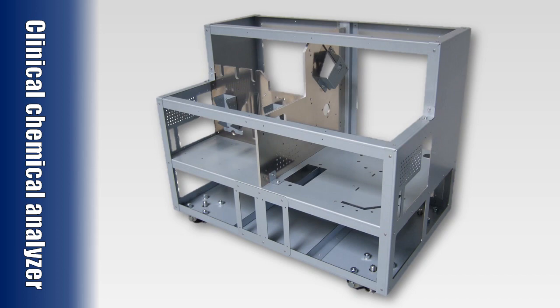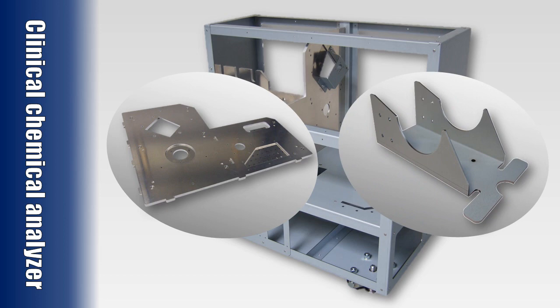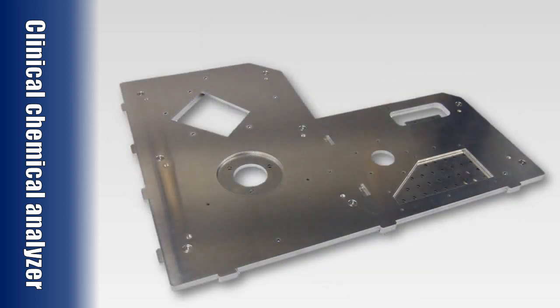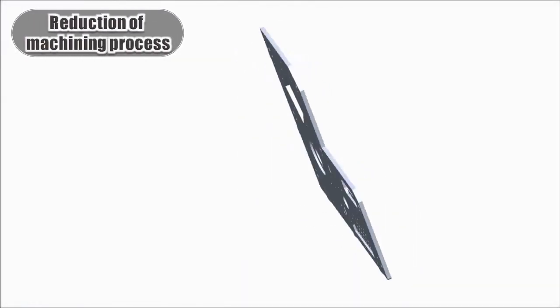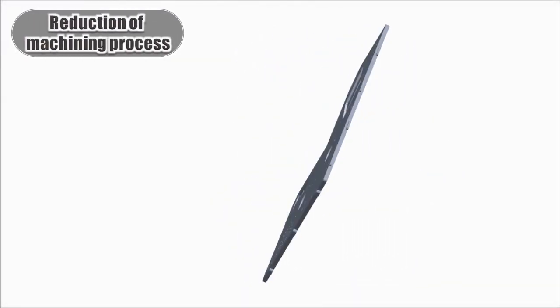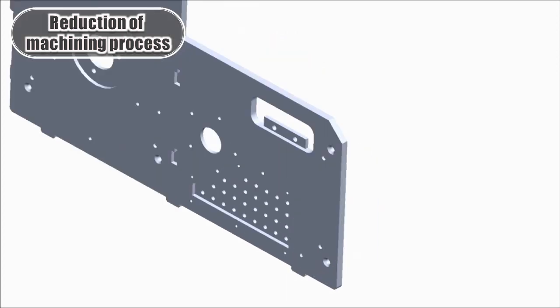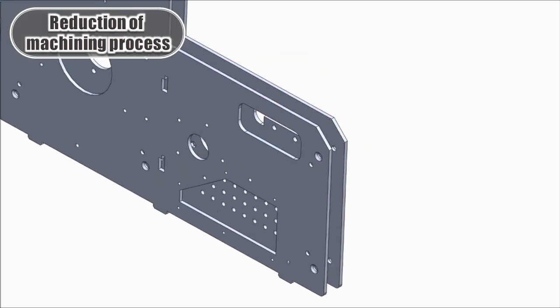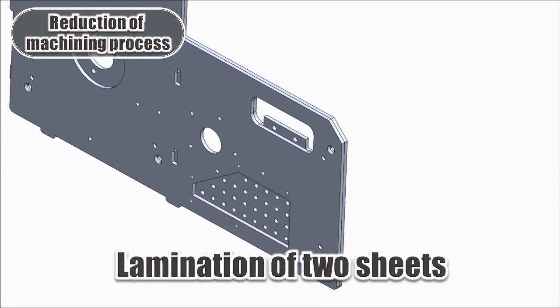First, let us introduce 2 cases for the clinical chemical analyzer. For the first case, we'll take the aluminum partitions used inside the frame as the example to show how we can reduce machining processes. In this example, we replace the machining process of 8 mm thick aluminum part to sheet metal processing by using 2 sheets of 4 mm thickness each.